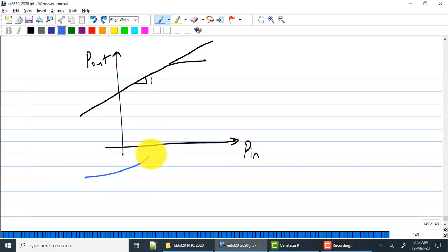Maybe some of you are seeing a lesser slope. Maybe some of you are seeing a higher slope than 3 by 3, right? All of those are possible. Most probably what that means is your amplifier is more nonlinear than what you expect. That's what I suspect. Because when your third order is dominant, you should see a good 3 by 3.